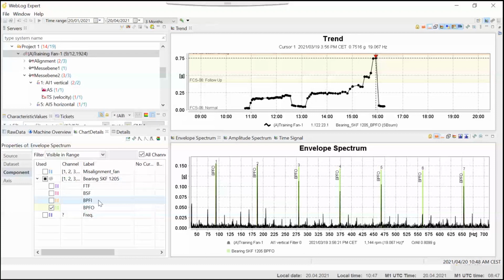It would depend on the type of failure that you were looking at. Mostly with a rolling element bearing failure, you could probably say, yes, that's likely to be a rolling element bearing problem, but most systems have at least one bearing at each end, and sometimes they have two bearings at each end, one thrust bearing and one radial bearing. So you need to be able to distinguish which bearing it actually is. And if you have something like a gearbox, there may be 6, 8 bearings in a gearbox. So there's quite a lot of decisions to be made to find out the right bearing to change.